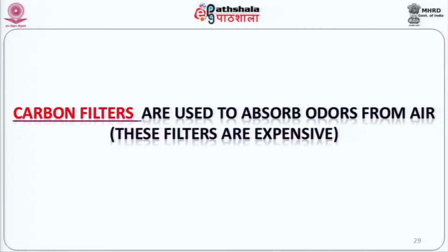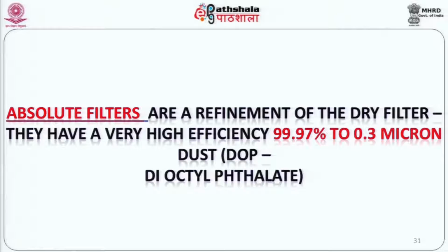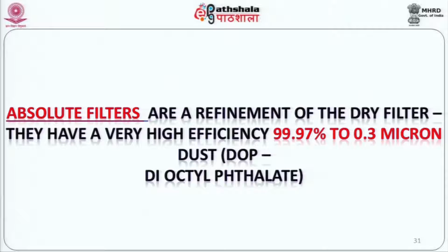But supposing you have a situation where you can't take a large quantity of fresh air for limitations like, let us say, the shelter being underground, or like the air conditioned area being in a place where you cannot draw a lot of fresh air, then you necessarily need to control odor by these kind of special filters which are called carbon filters. Better than these carbon filters, one has absolute filters. These filters are the same dry filters. They have a very, very high efficiency. Their efficiency is as good as